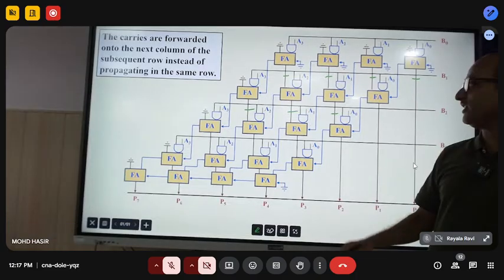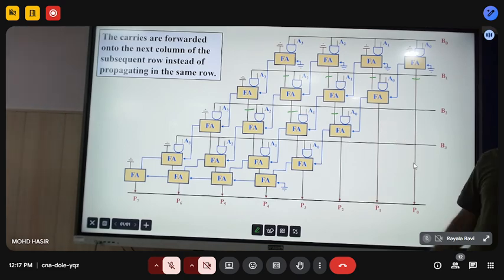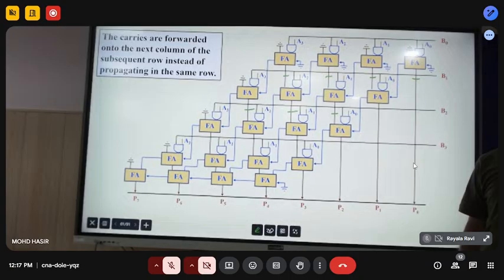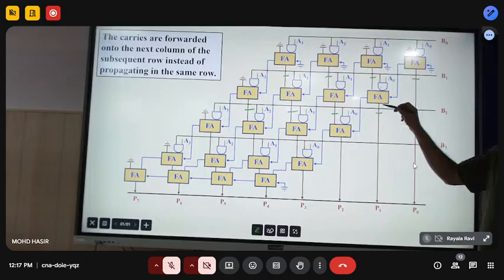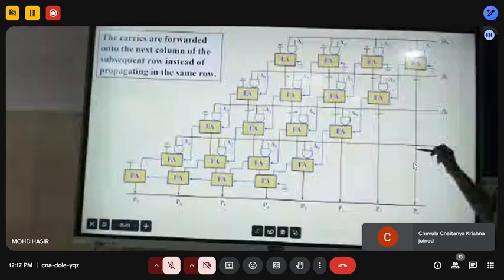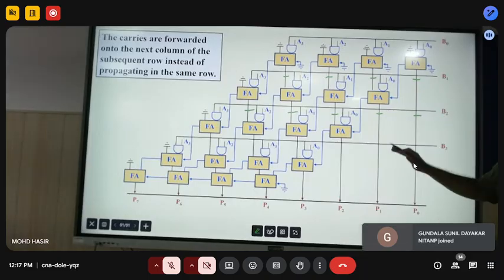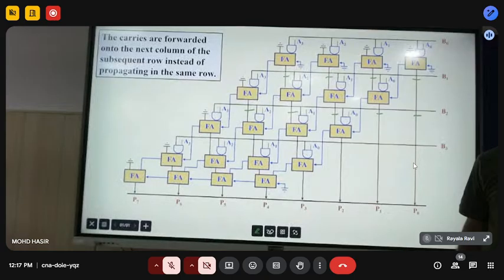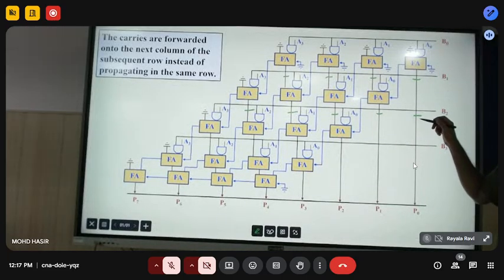Okay. So what will happen now with this? Do I need to add a flip flop here? Yes or no? Tell me confidently, yes or no? If we don't add it, then this result will be 2 clocks delayed and this will be 1 clock delayed. So there is a result mismatch. Okay. So if this is delayed by 2 clocks, this should also be delayed by 2 clocks, so that the result will be output at the same time instance. Otherwise, there is a bit mismatch. So even though you are having this as a fast path, you have to insert a flip flop. There is no choice. Alright.